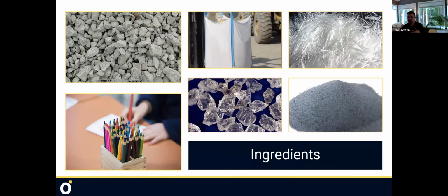So you have, I don't know, 3 to 5%, something like that in resin. The rest is natural materials, 80 to 90% natural materials, depending on the build. And you have an engineered stone rain screen panel, right? The Petric line looks and feels like a fiber cement to a degree, but it feels a little bit more classic, a little bit more stone. We can add slate and quartz and other stones to that to make a really nice, natural feel.